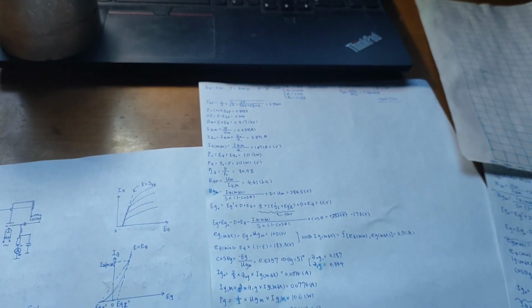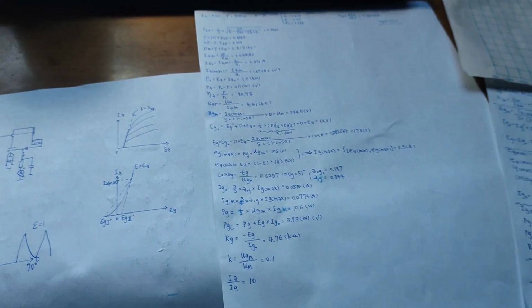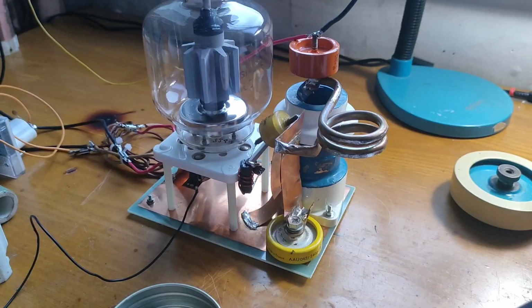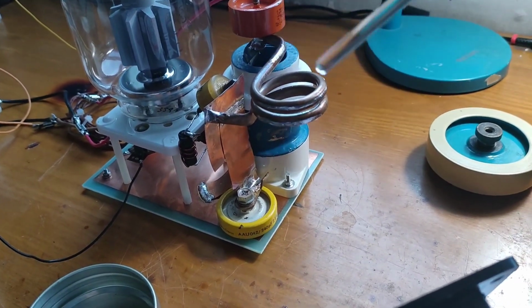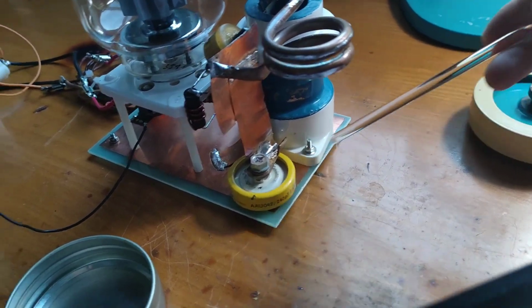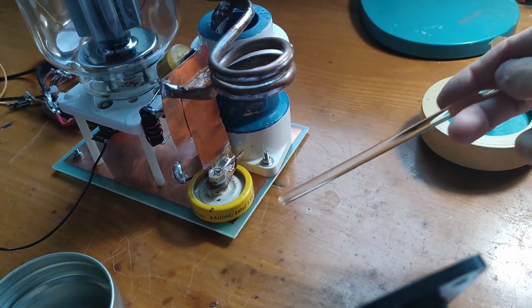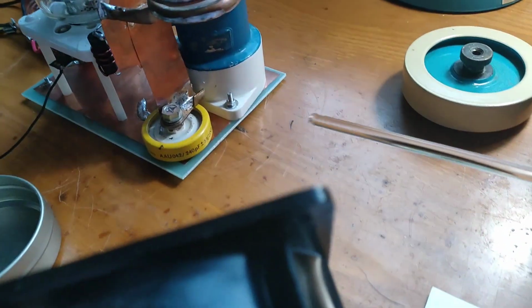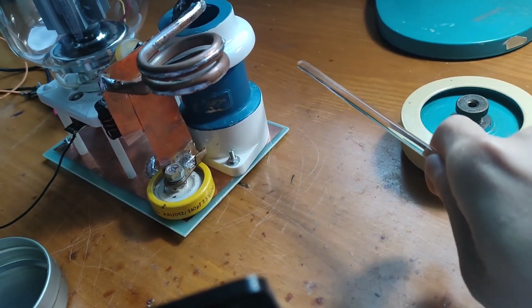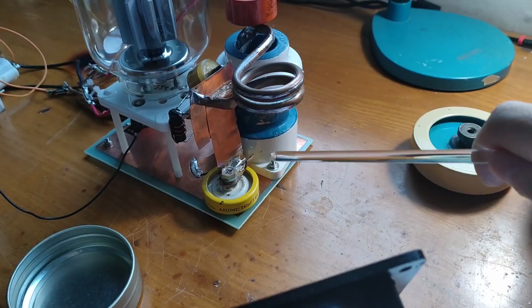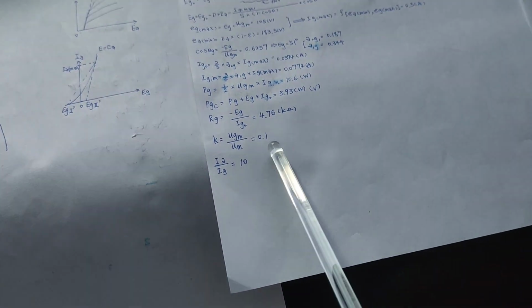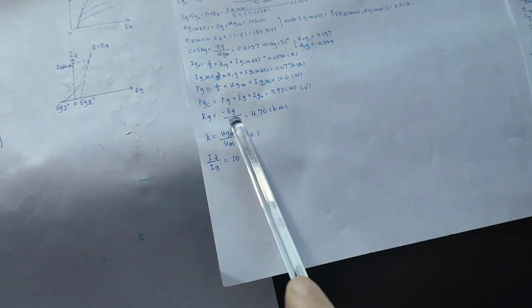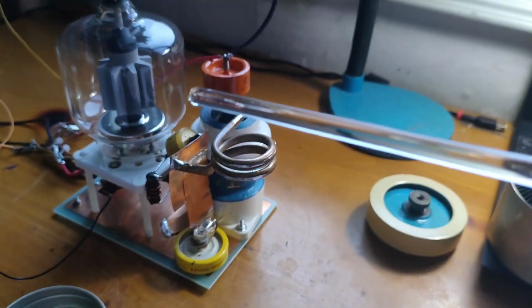We just went over all of the calculations we need, and now let us talk about how to tune the oscillator. In this situation, it's a Colpitts oscillator. You can see this capacitor together with this one actually forms a voltage divider for driving the grid. And you can see 240 picofarad, and this one is 68 picofarad. So the feedback ratio is actually larger than 10%. I recommend using 2 to 2.5 times this value. That will mean 20 to 25% feedback ratio to get a rather stable oscillation.